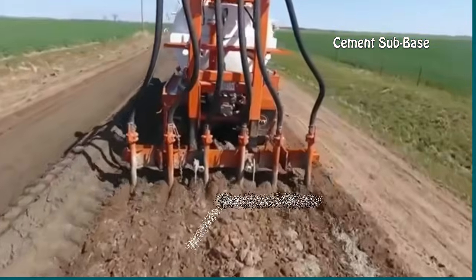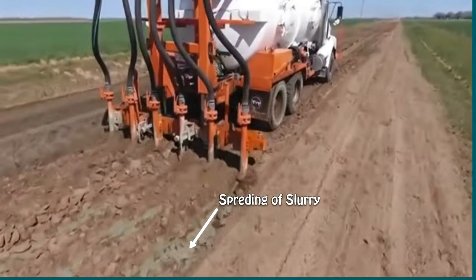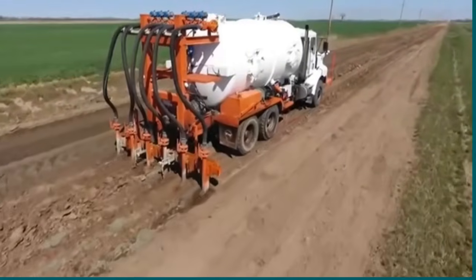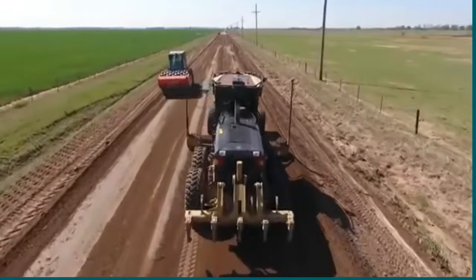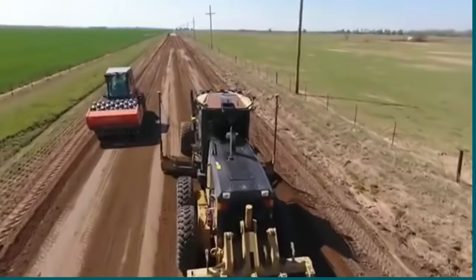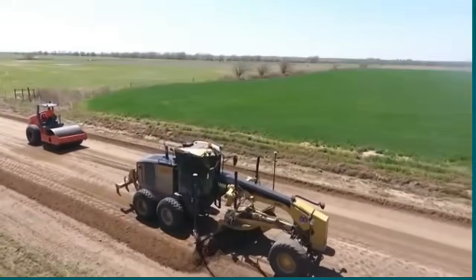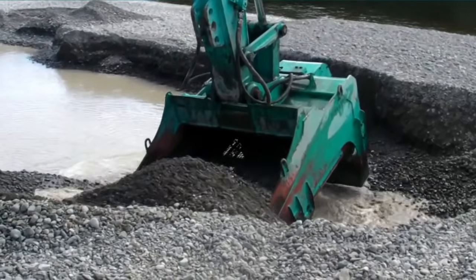Cement-bound subbase is a cost-effective way to build a heavy-duty, durable pavement, fast. It offers an alternative to traditional flexible materials. The binder material can be a rapid setting like cement, or slow setting materials like PFA and slag. However, the unbound granular materials are the most commonly used for road projects.